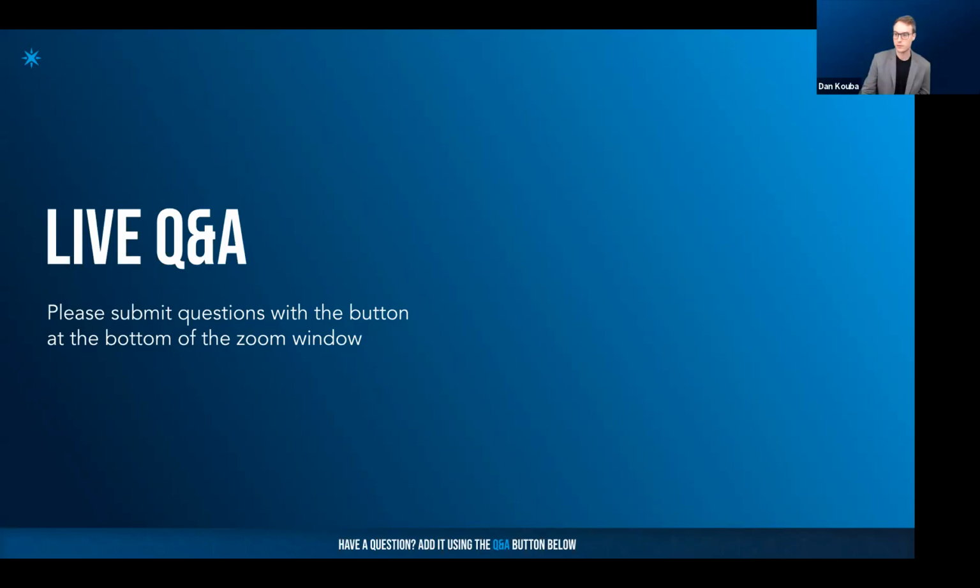Yeah, sure. So security is built into our device operating system at our factory. So we have security between our device, what we call Device OS, the operating system that lives on the device, and our cloud. That is based on TLS. In our case, we use DTLS as we're using UDP, which CoAP is based on, for the communication to the Particle cloud.